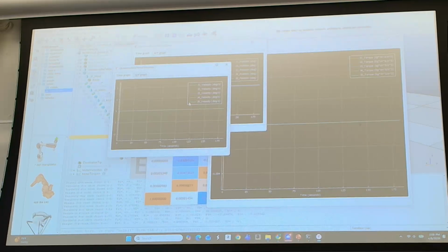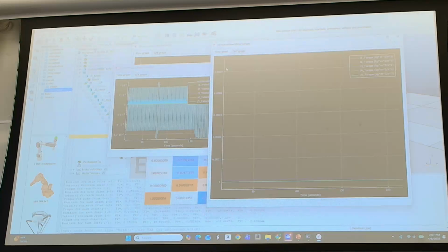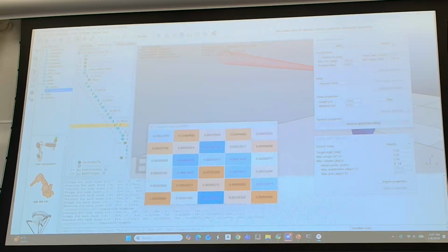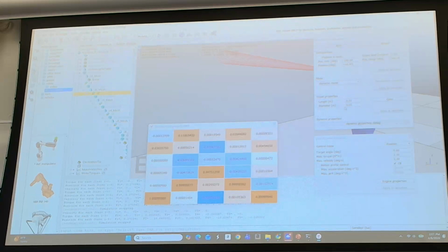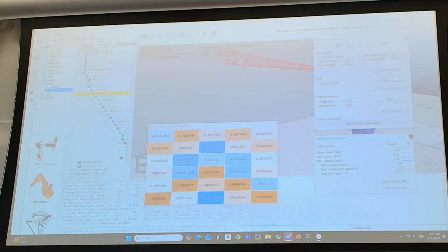Okay, so the last thing we're going to talk about, we're wrapping up: the Lagrange. I've got 7 minutes real quick, and I'm going to use this to explain what's going on with the Lagrange. So let's see, did I rate limit these motors? Let's take a look real quick. Joint 2 tends to be the one that's doing a lot of the heavy lifting if I'm moving that planar spot. So if we come over here, I gave it a max velocity of 2.5 degrees per second, with a max torque of 2.5 newton.